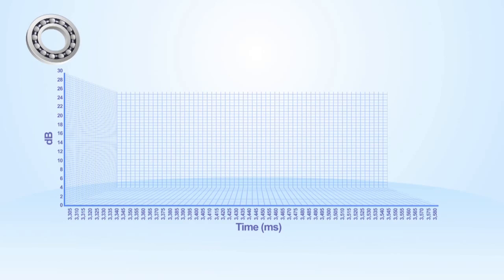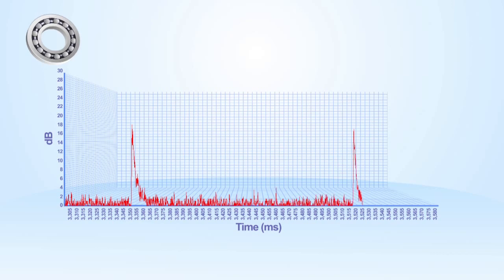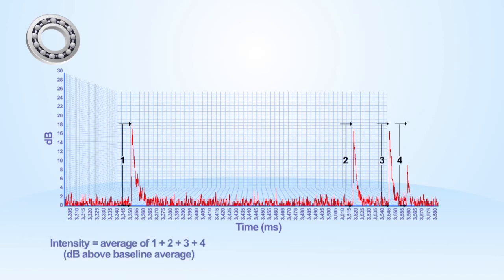When a rotating element moves swiftly, there are plenty of frictions and impacts to monitor. However, when the speed of rotation is slow, there is little data to work with. Consequently, along with dB, the distress parameter has been divided into 3 parts: peak, intensity, and extent. Peak quantifies the largest spike of power released from the source of impact. It is always the highest value of energy measured and is most useful as an indicator of a significant singular event.